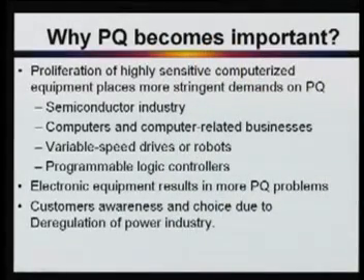If you have higher harmonics, one obvious effect is that the core loss will be more, because the frequency is higher than your normal supply frequency and is added on your fundamental component. This leads to more loss and more heating, and the heating may also reduce the lifespan of your equipment.